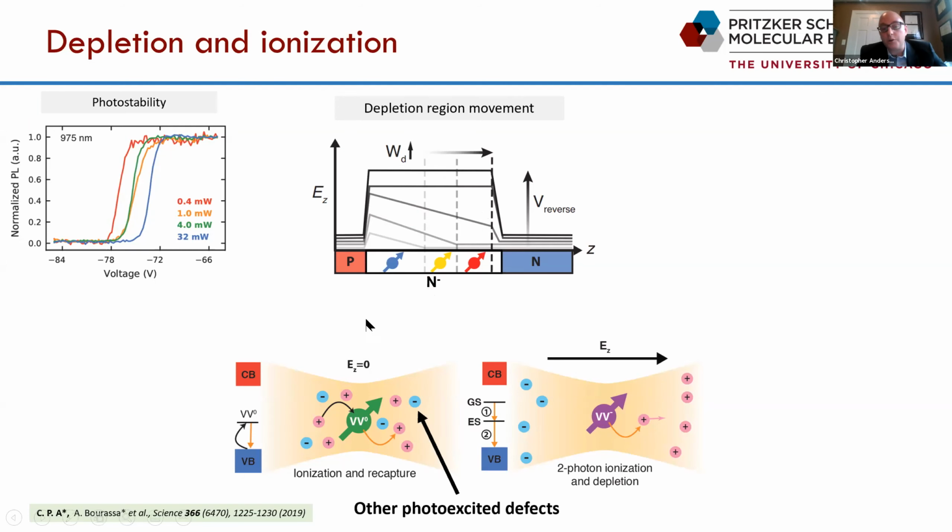It's actually slightly n-type doped, such that the electric field profile in the depletion region initially only forms at the p-n minus interface, and only with increased reverse bias does it move its way through the intrinsic region of our PIN diode and, at the end of the day, drop uniformly across it. So as a function of where your defect is in depth inside of this diode, you have to wait a little bit, applying more reverse bias, before this field profile makes it to where the defect lives. This minus 75 volts corresponds to where the defect is in depth.